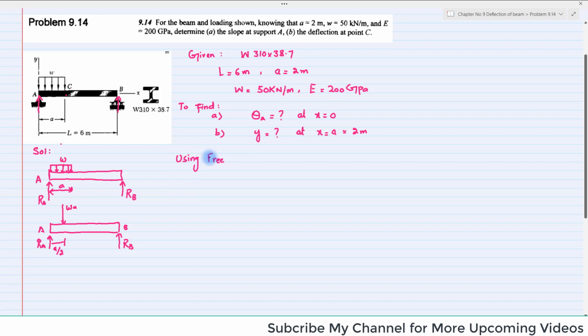Free body diagram of beam ACB. Clear? You can see that RA plus RB will be equal to w into a. Clear? This equation is due to sum of all forces along y direction is equal to 0, with upward as positive. Now we will apply the second equation, that sum of all moments about point A is equal to 0,